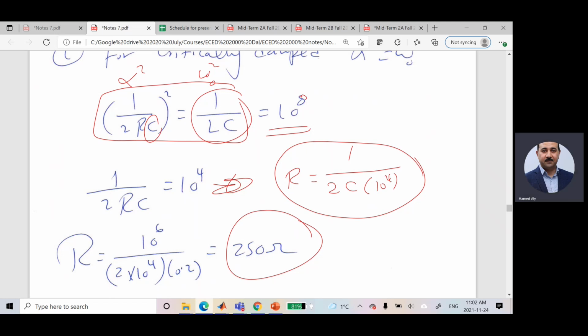Do you have any questions, guys, for this problem? Yes. If RLC is parallel or series, S1 and S2 remain the same, right? Yes, S1 or S2, based on what we have already derived for parallel or series, is equal to negative alpha plus or minus the square root of alpha squared minus omega naught squared. I have similar equations for parallel and series. The only difference between them is alpha and what you are going to find.